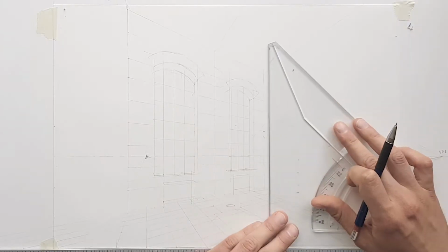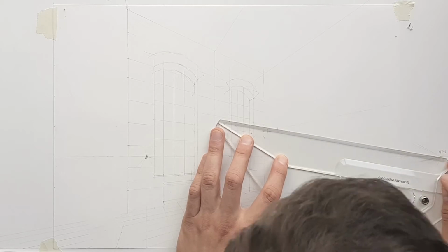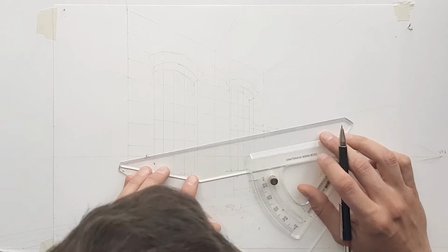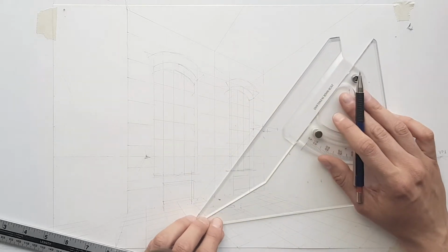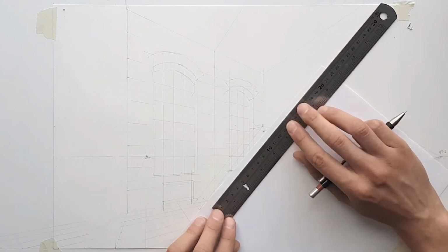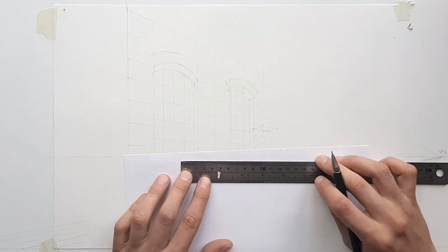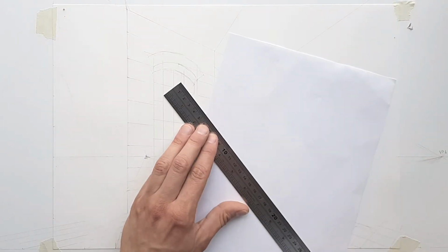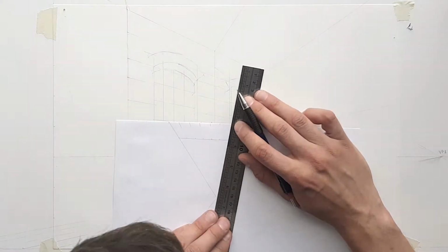So next I'm projecting my landing, which I've indicated on the ground floor, but now I can project it up to the mezzanine level, and then I'm connecting the nosing of the stair with the landing. For this next bit, I'm using an edge of paper to mark up a 10 centimeter line in front of it. And using this trick here, I can divide the edge of the paper into 10 increments. This is just to save me using a calculator, and it's a bit more accurate as well.